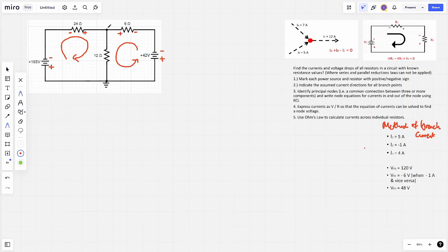Now at this point we've got 2 sets of currents. We've got one current going from this battery source up to the right, and another current going from this battery source up to the left, and that's going to meet at this node. So as the current goes through, there's only one way, which is downwards. So there's 3 currents. We're going to label them I1, I2 and I3, and using our key we can say that when the currents enter the flow, they must equal the current exiting the flow.